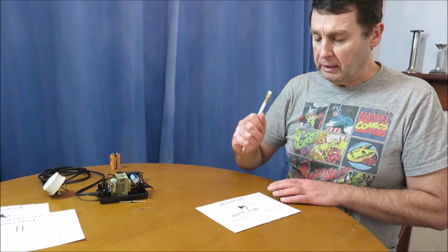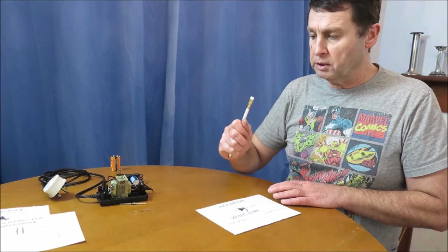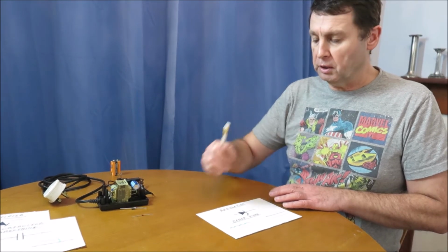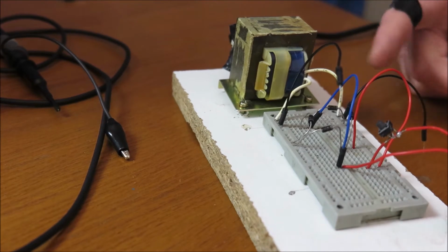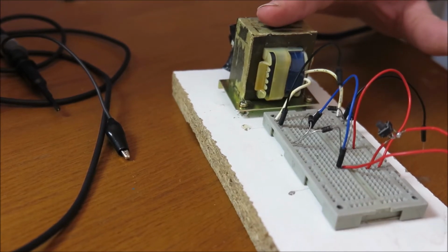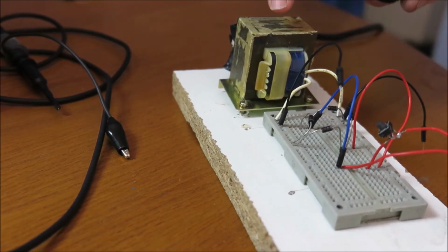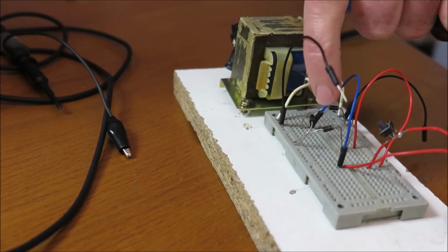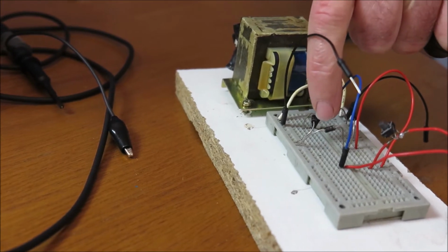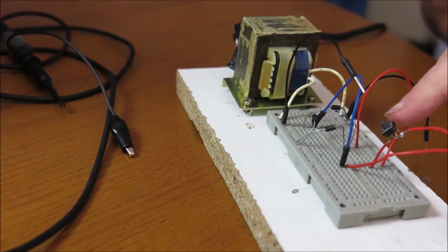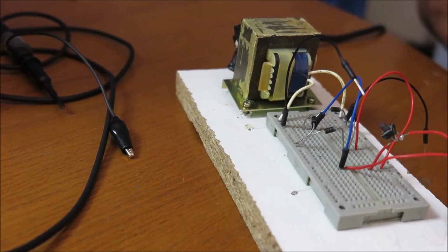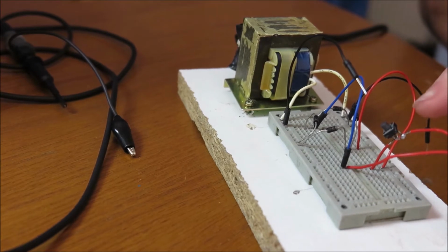So next, what we're going to have a look at is those components when we connect them across the oscilloscope. So we've connected up now our power supply. I've taken the transformer from the other power supply. So we've got a transformer, we've got a bridge rectifier made of 4 diodes there, and we've got a smoothing capacitor. Now I've put a switch in the smoothing capacitor so we can switch it in and out of the circuit to see what it actually does.